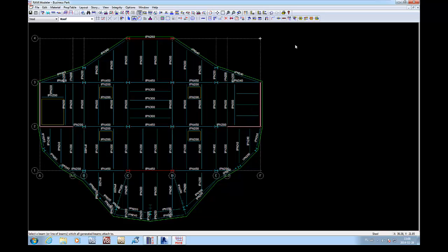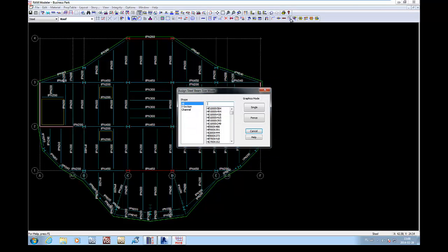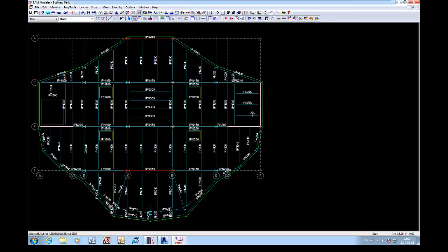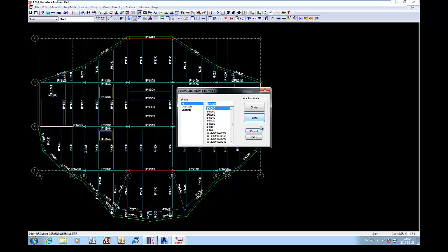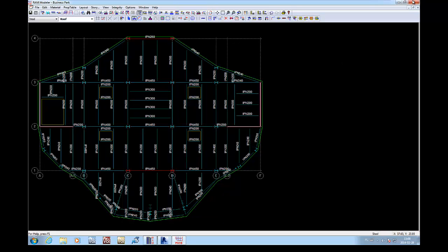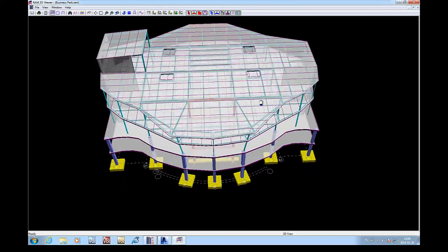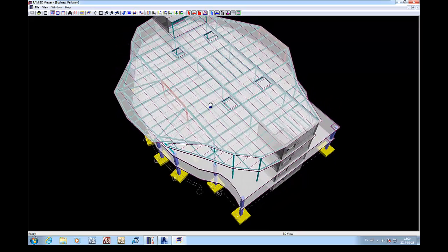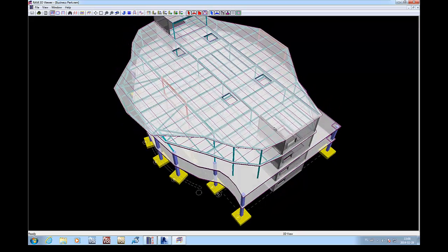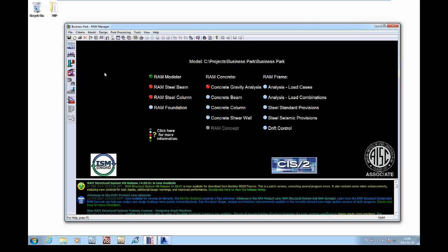So beams are added. Now we have to add sizes. We are choosing it from our tables. Okay. So the beams are modeled. We can see the 3D representation of our model, how it looks. We can see the changed model beams from Revit and added beams from our work right now. And now we can update the ISM repository again.